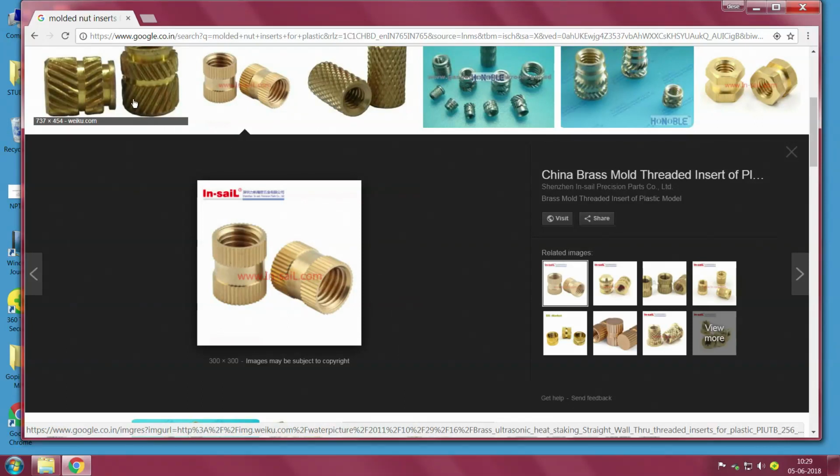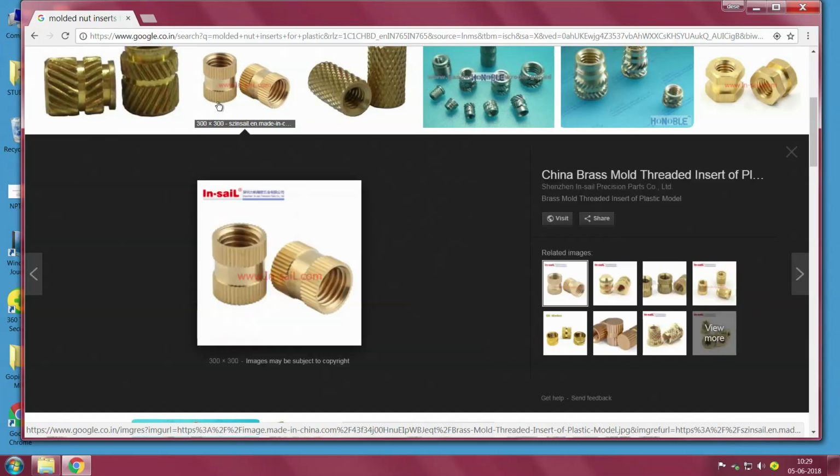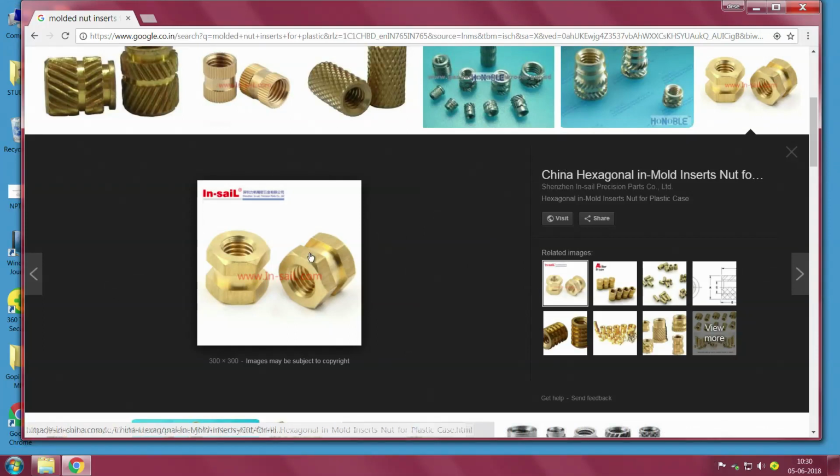You see that one had that knurling, but it looks like a herringbone gear. This one has straight knurling and it has a small step inside. So maybe it is patented, maybe not. This could be a very common thing which you can even make: take any long hexagonal tube, they are usually available up to 50 to 60 long, part it, and then afterward cut a groove, and you have an object that can be easily used in injection molding.